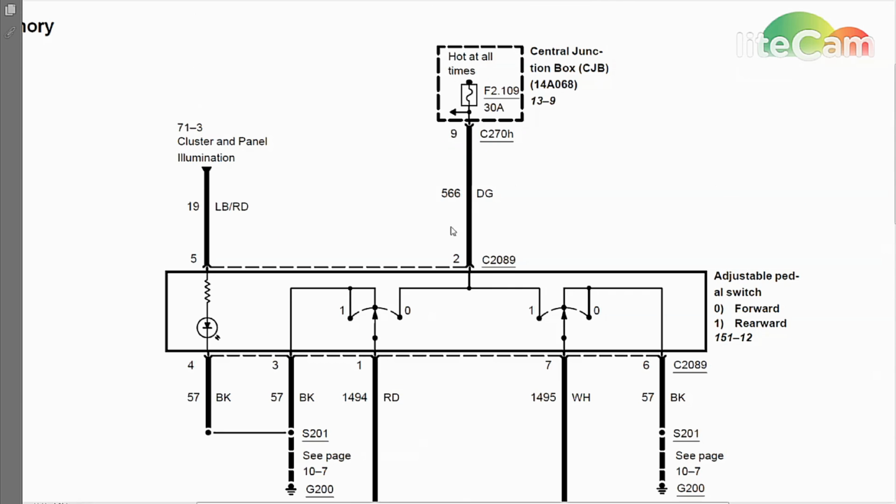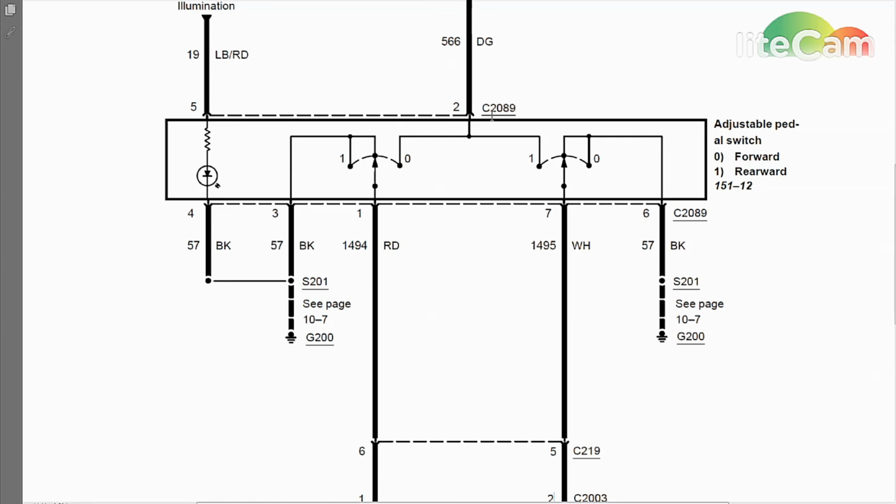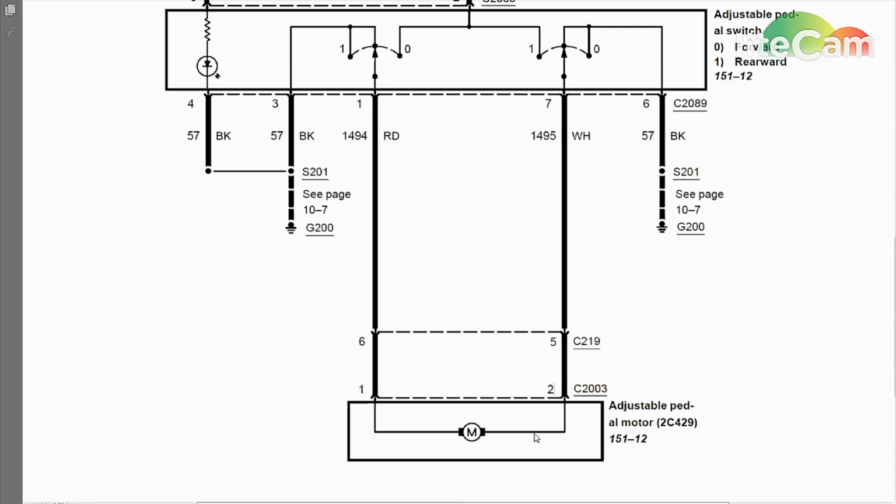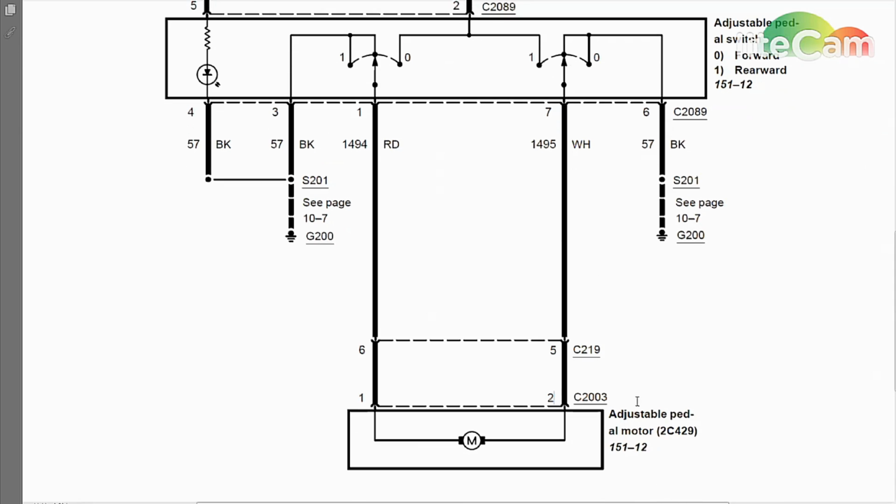Now between all these checks on here, that's a very simple circuit like I said, but just pulling this connector off of here and doing a few simple input tests on here, you can really diagnose this very, very fast. There's a few inputs and just a single output here to one load, and that's all there is to this circuit. So it's very simple.